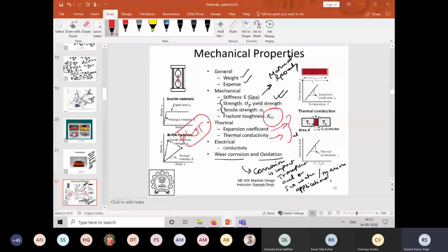There will be a lot of residual stresses in the system. So coefficient of thermal expansion should be low. You will get thermal stability. It will not deform. There will be no deformation gradient, and there will be no residual stresses. So thermally it will be stable.